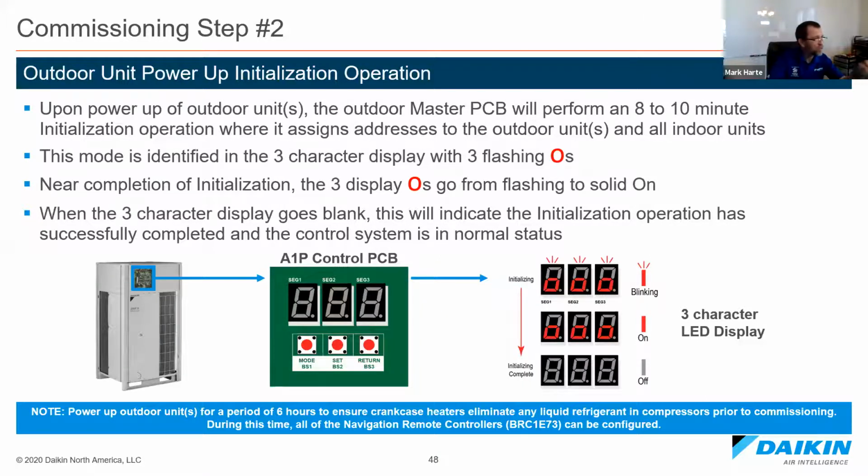Now, what you'll see on the LED display during initialization is zeros. You'll see 3 of them and they'll be flashing. Okay, this is normal. Don't do anything. Don't hit any buttons. You don't need to. It's going through and looking. Near the end of initialization, those 3 flashing zeros will turn solid. That's good. You want it to do that. When it's done initializing, that display will go blank. That's good. That means there are no issues at this time.